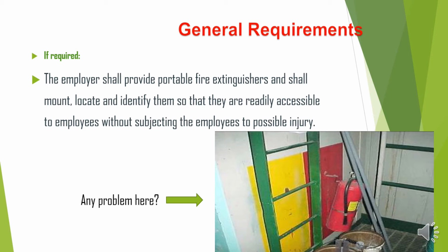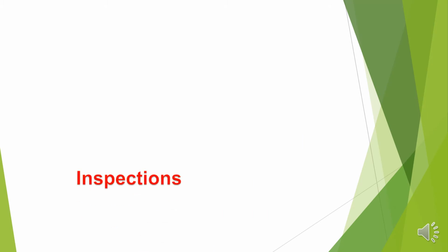the answer is yes. We can see two long steel bars on them, on the fire extinguishers. So if you want to use it, you first have to remove those metallic bars, and it could be very heavy for you. You can ask another one to come to help you. It will take a lot of time. So it's wrong. We have to report an OVR that something is wrong here. There should be no obstruction for fire extinguishers, so we can use them simply in case of fires.